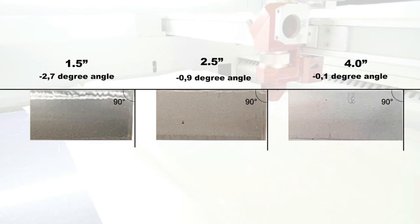So here we can observe the 3 pieces of cut acrylic, and when using the 1.5-inch lens we can clearly see that we have an angle. And with the 2.5 the angle is still present, but not much, in fact it's rather okay. But if we look at the 4-inch lens we can see that there is basically no angle at all. So, what happened?